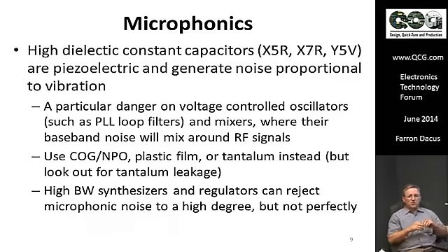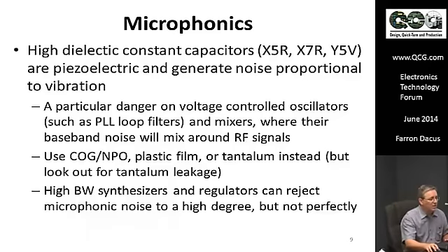So the answer there is use low noise supplies to start with, actively low noise, and then use these COG type caps when you can get away with the small capacitance. When you need more capacitance, go to tantalum or film. Don't go to the high dielectric solids.